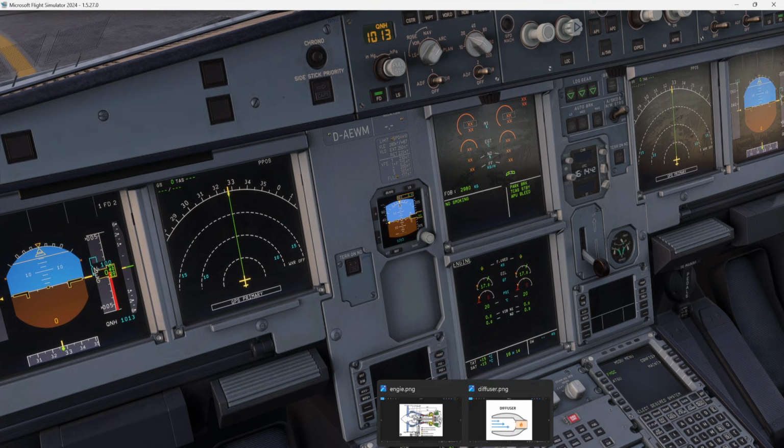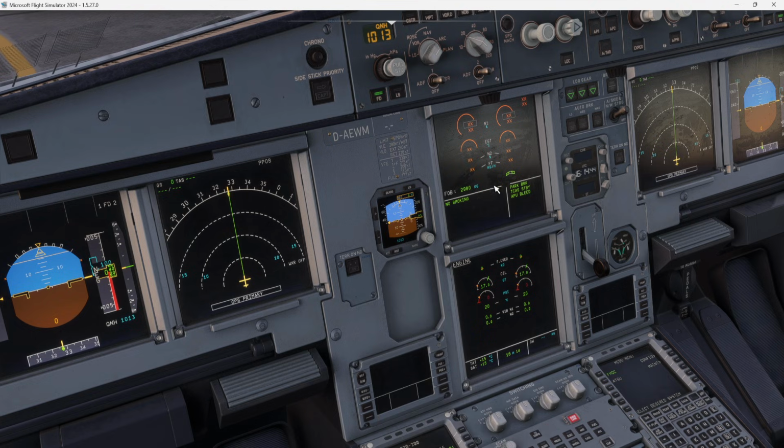I'm going to give you a picture. Just remember with me, this is the N1 and this is the N2. If you go to the jets page here, you will have the vibration of N1 and the vibration of N2. These parameters are important, and so is the EGT. For now, remember just N1 and N2, because we need them during the startup. First, we need to understand how it works in order to understand how the startup goes and what we should monitor. Let's go back, my friend.